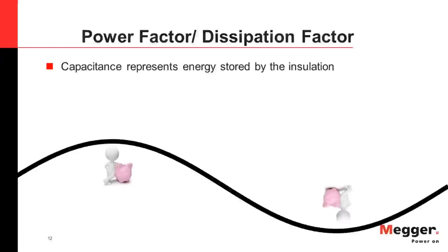In fact, after a half cycle, the polarity of the applied voltage changes, so the energy stored via moving atoms, molecules, and charge starts moving back until the next half cycle and so forth. So there's this constant back and forth exchange. And these ongoing so-called polarization processes contribute losses, as does conductivity that results from leakage current.